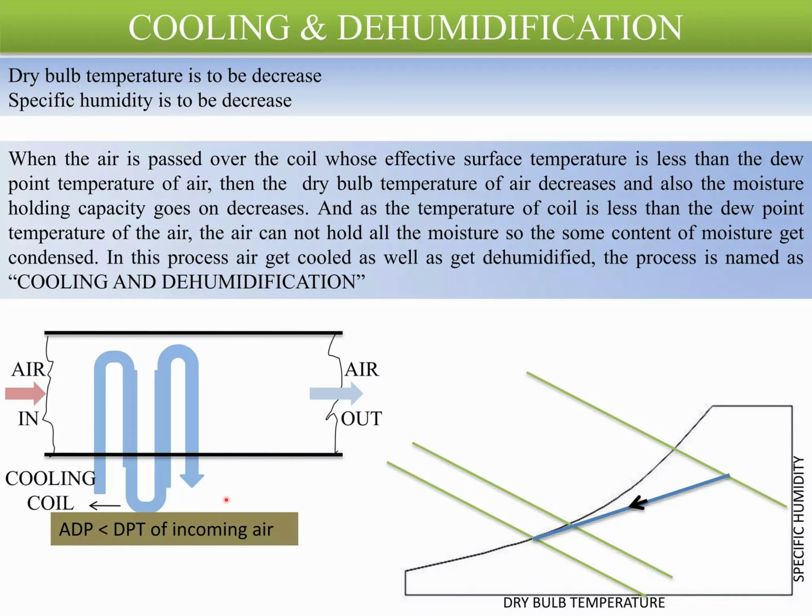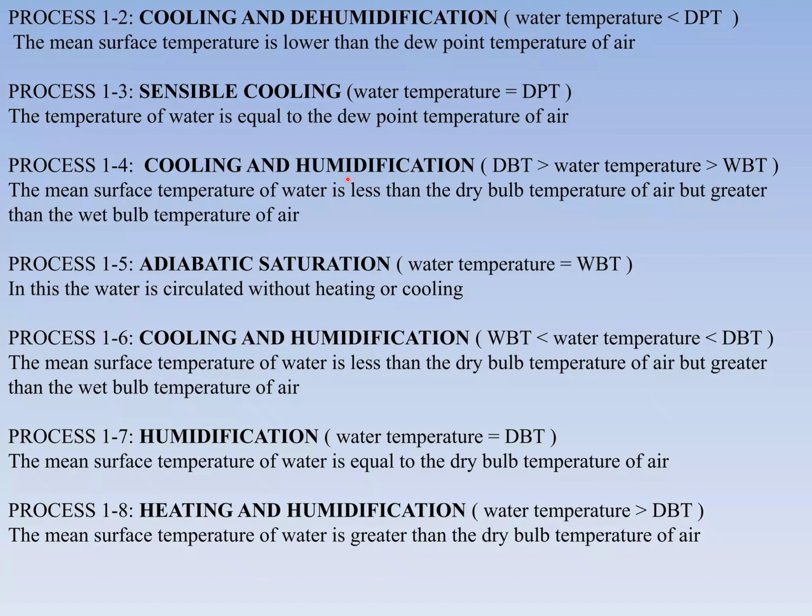In the cooling coil, cooling happens and dehumidification happens. Dehumidification means our moisture is getting converted into water and our room is dehumidified. This is the scenario. So this is the overall summary that we have already discussed.